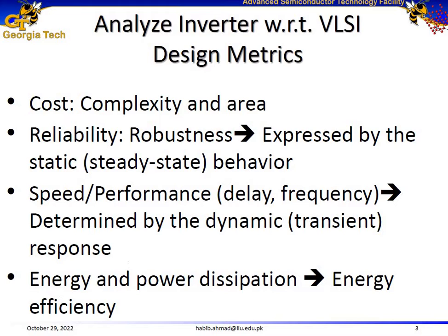Yeah, I mean the kinds of capacitance are the gate to bulk or gate to channel capacitances, the diffusion capacitances, and the overlap capacitances, right?